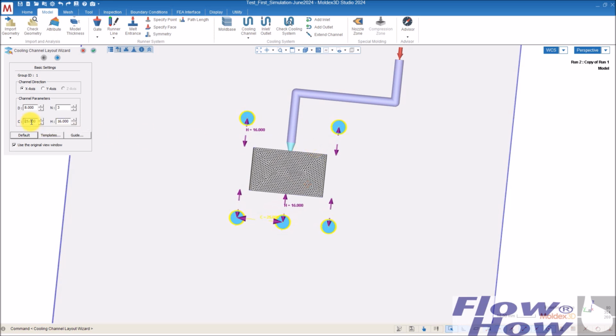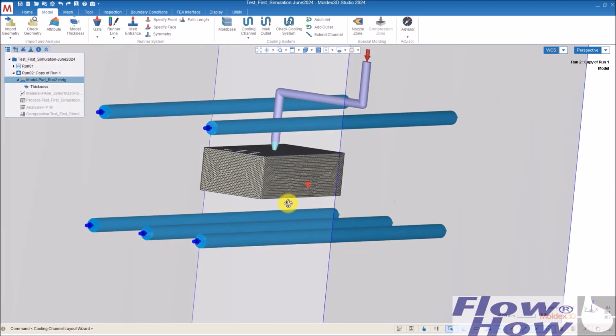And maybe I'll use the scroll still. I'll go a bit longer out and a bit away. In simulation, it's a good idea to choose not that perfect cooling from the start, maybe, because if you can show that you can make good parts with very simple cooling, then you have plenty of room of making the mold even better in reality. So in this case, I'll say, okay, a cooling like that is okay. I'll try with that.